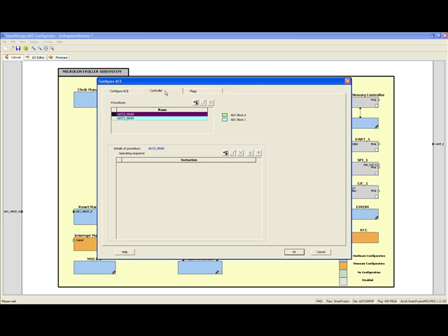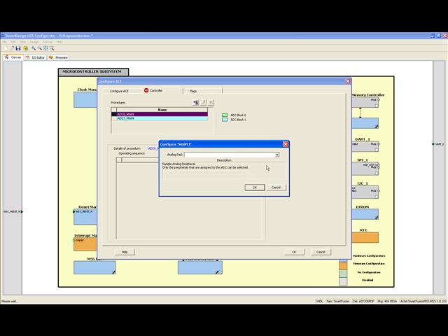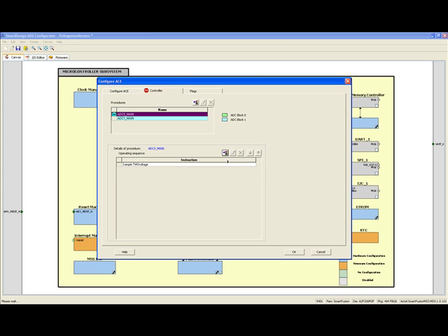The Controller tab opens and lists the ADC0 main and ADC1 main sequence procedures. Click the Insert Operating Sequence Slot button on the Details of Procedure window and select Sample. The Configure Sample window opens. Use the pull-down and select TM0 voltage and click OK. Click the Insert Operating Sequence Slot button again and select Restart Sequence. This sequence keeps a continuous sampling sequence in operation.